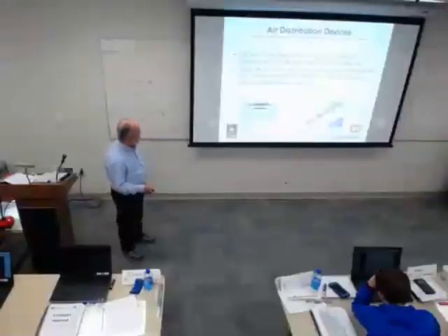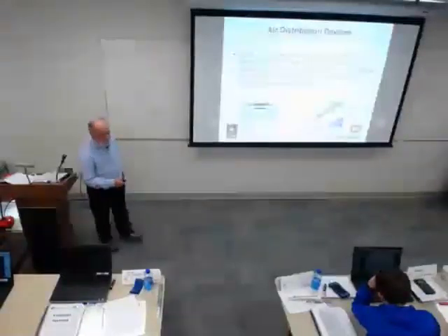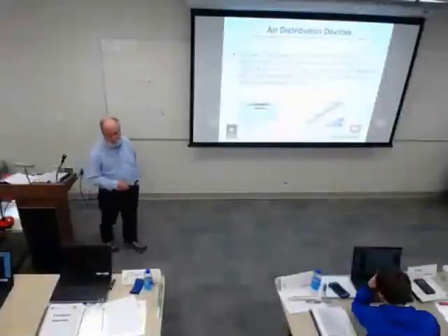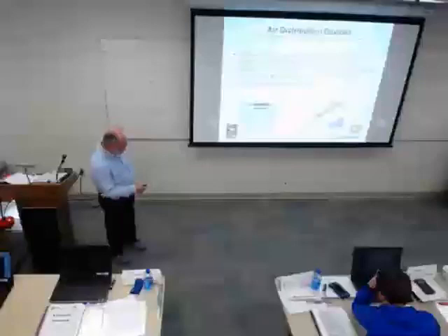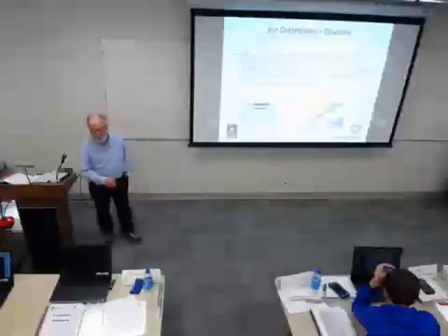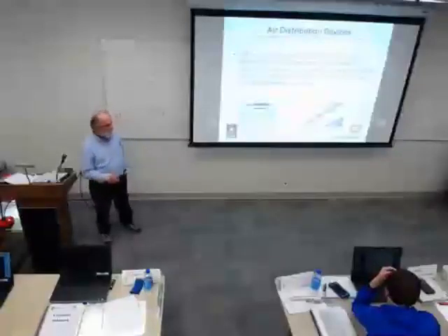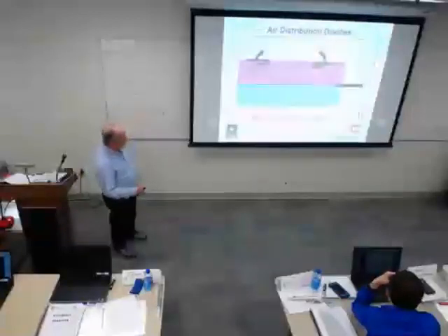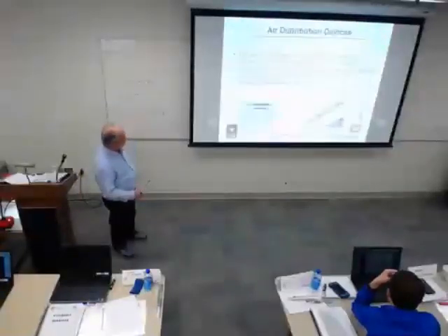You see them a lot because right now they're cheap, but I expect their use to drop off because they just don't perform well, especially with VAV systems. This right here used to be real popular. I like them because they allow you to do a lot with directing the air and getting the momentum where you need it, but that's a design course. Whatever we get on the job is whatever we got.